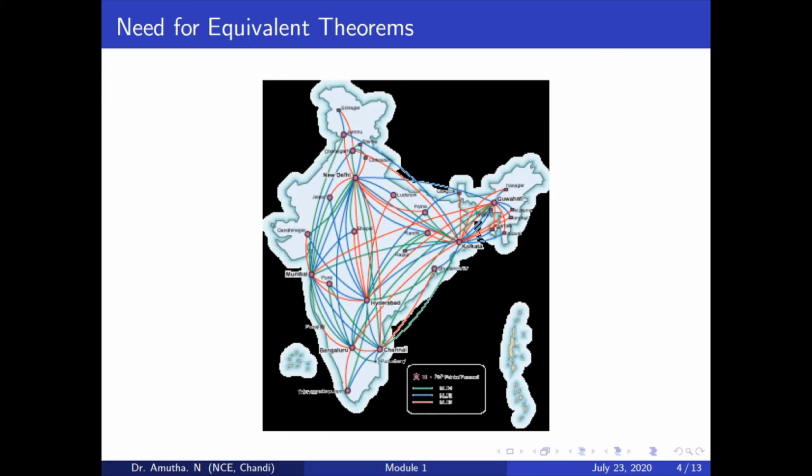Okay, for that, the first thing is we have to find Thevenin's impedance, right? For that, we have to make all the independent sources zero, while dependent sources remain in the network. Only independent sources have to be removed, right? How can you remove the independent sources? By short circuiting the voltage source and open circuiting the current source, right? Removing all the independent sources and keeping all the dependent sources in the circuit, we try to find out the impedance.